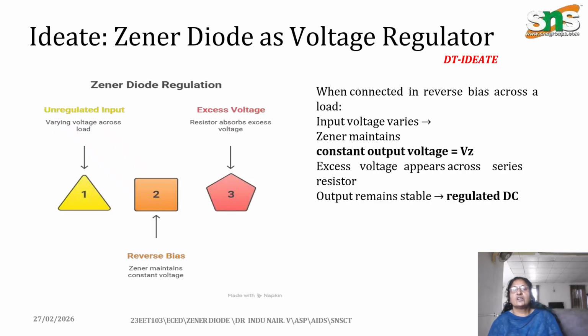So, the Zener diode as a voltage regulator. Vz, or Zener voltage, is the regulated breakdown voltage. Iz is the Zener current, the current flowing through the diode. Data sheets list Iz minimum for breakdown to occur and Iz max to prevent damage. Power rating Pd is the maximum power dissipation, calculated as Vz times Iz.